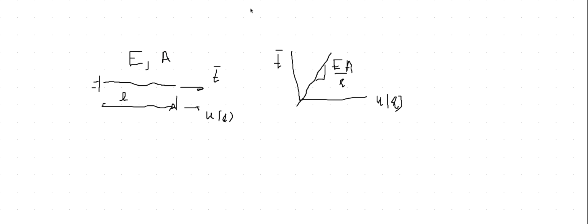So imagine I'm going to take a case where A is equal to 1. This is the usual decision when I'm making a 1D problem. I'm going to take the case where L is equal to 1. So instead of this guy, when I divide by A, this becomes sigma. And if I divide this by L, this becomes my epsilon. And L equal to 1, A equal to 1 is kicked out. So there's only one thing left, giving me the slope, which is the Young's modulus.